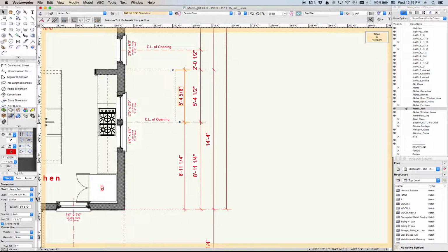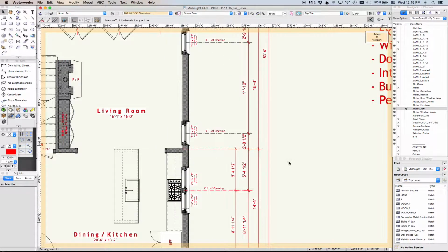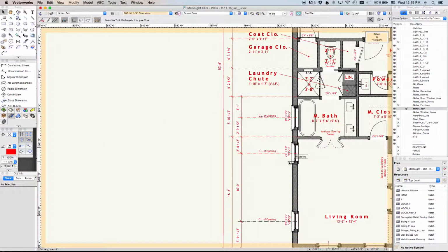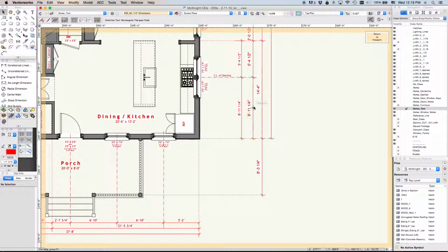Cabinetry is another story. So for instance, this right now is set on the tolerance so that it does show 1/8 of an inch, but if you go over here to the settings, precision, it's set on 1/8 of an inch precision. A lot of times I will force it to 1/4 inch precision. You can see it adjusted it, and a lot of times I'll look around and go back through and check, and if I see some that came in at 1/8 inch scale, I'll force the precision setting to 1/4 inch.